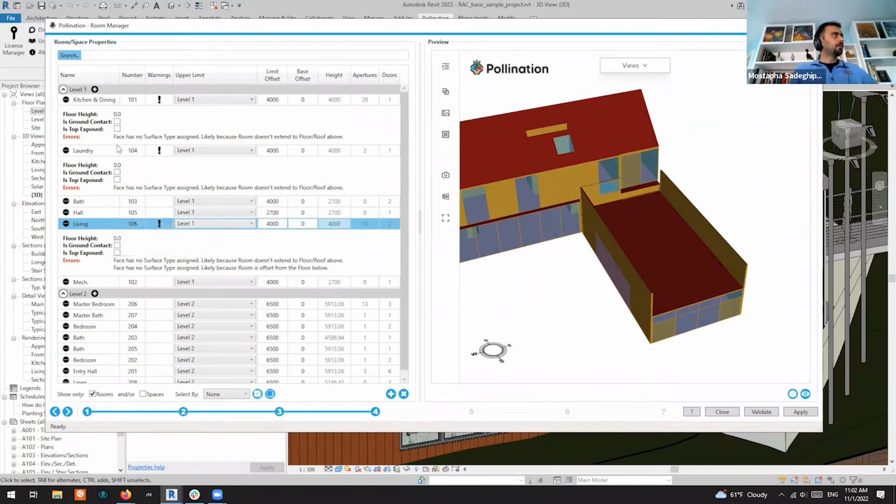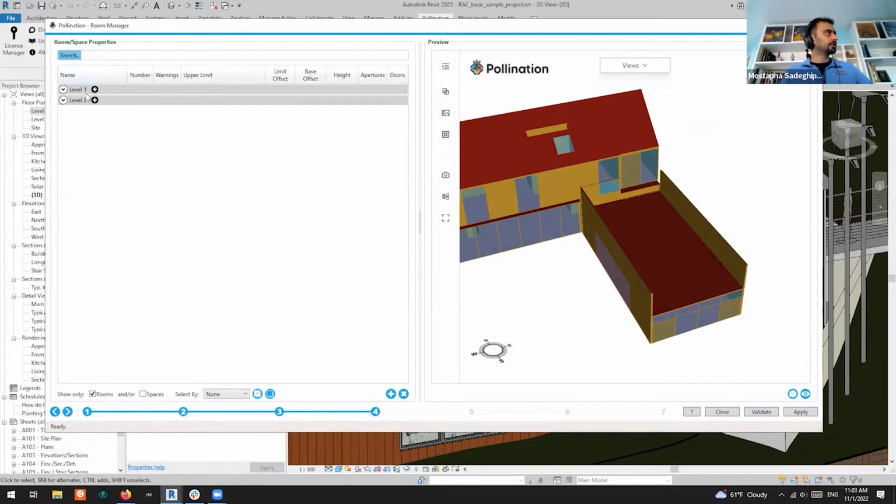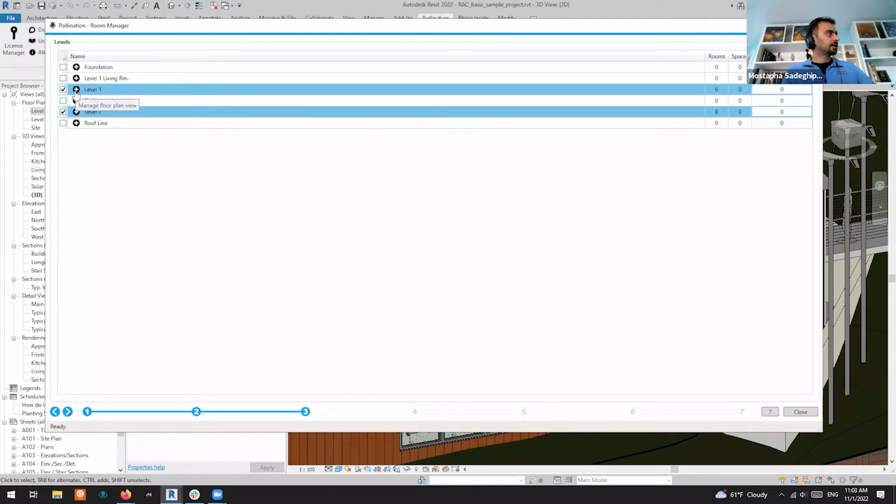But before doing that, we have built what's called a view template. I think if I'm doing it right, for Pollination, you can quickly come and you see it's here next to every level, either here or you could have done it here. There is a plus sign either in step 3 or step 4. If you're using an older version, this shade context might be here at step 3, I think. Sorry, hopefully that doesn't confuse you. We moved the context now after the room again because people asked for it, and I think it makes more sense.